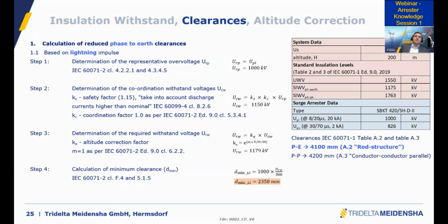If you look at the typical residual voltage for surge arrestors, let's say, actually it depends, let's say 192 kV rated, the residual voltage is in the range of 400, 500 kV, something like that. So there is a significant safety margin between the BIL of the system and the typical residual voltage of a surge arrestor. And as I mentioned, it's always possible to go even below.